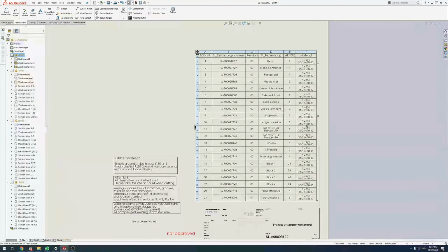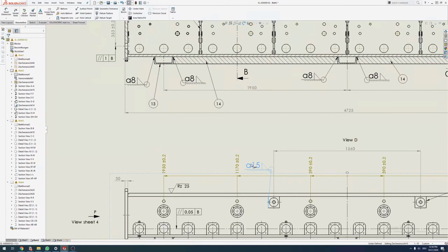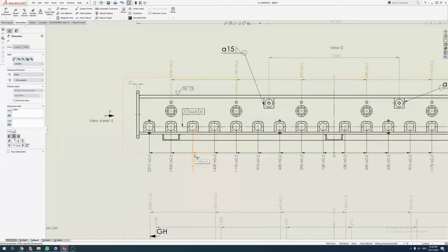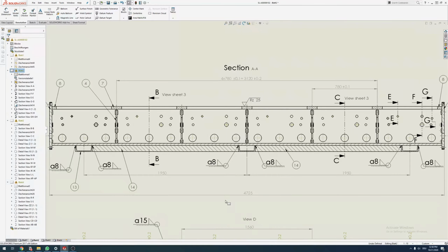When you weld A15 or A8, because of the thermal stresses there will be warping and there will be changes. What you want to have in the end after welding are these measurements here. You don't care before that. You want these, and whoever is manufacturing this has to make sure this correlates after they weld. Maybe they cut the parts a bit bigger, weld, and then machine it down to the measurement, to the size you want.